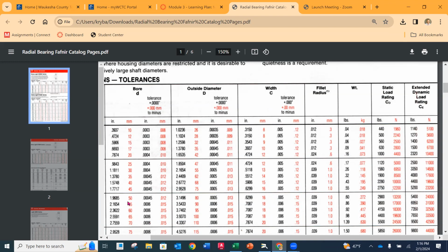If we would go down to 1.48, which would be 1.57, right, is the lowest. If we go over, we're not meeting the minimum dynamic load rating. Okay, so all three have to be satisfied. You have to have your minimum dynamic load rating, your static, and then also the shaft diameter. All right, so in this case, the dynamic load rating is dictating. So our shaft is just going to have to be bigger. So you might have to do some juggling around, if you would, in accommodating a larger bore bearing in order to get the life that we need.